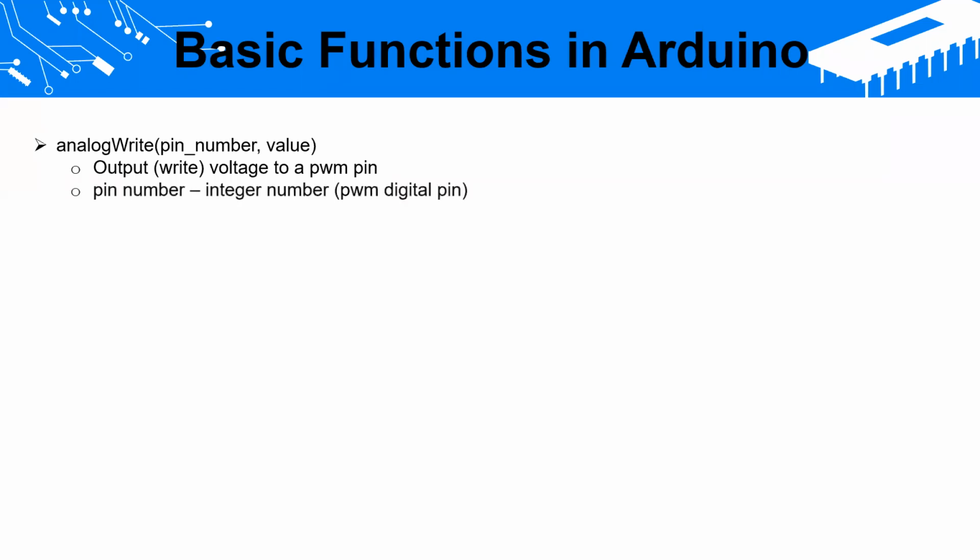So in that case, we are faking this analog world, and we are using PWM pins, right? So the maximum value will be 255. So you can write 0 to 255 values. Then this voltage level, if you write 0 or 255, it doesn't have a very good precision, but it is almost 0 voltage and almost 5 voltage, right? It has a kind of error.